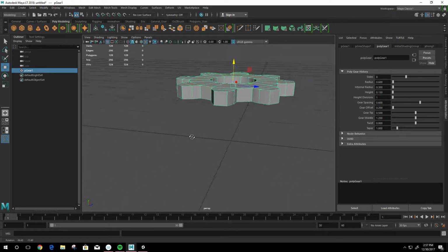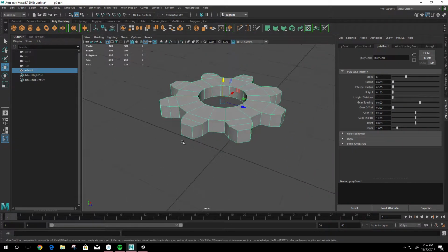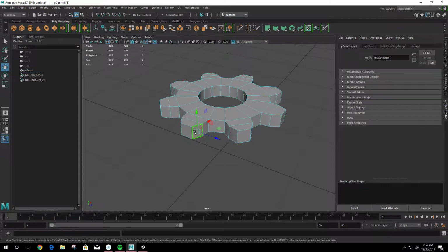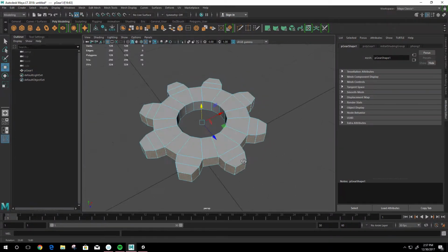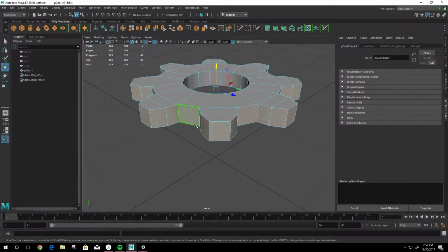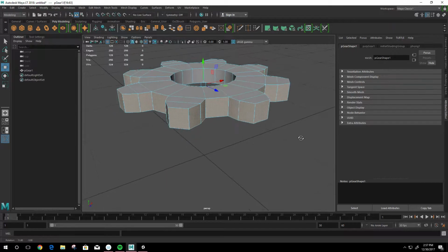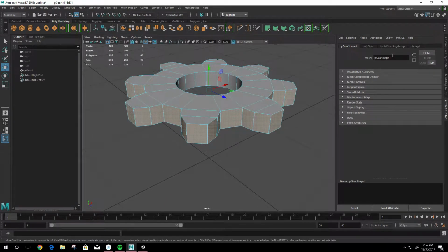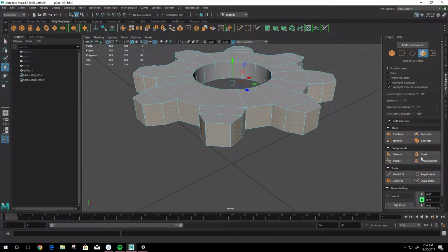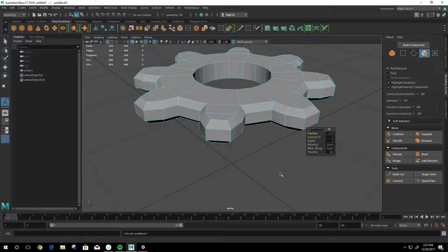It's pretty sharp edges. Yeah, why don't we try beveling it? Let's see if we can get this edge loop. Yeah, there we go. Just right clicked, hit face, picked a face, and then double clicked, and I got that whole face loop on the side there. Let's go over to the modeling toolkit. We've got bevel here. Click that. That's pretty cool.